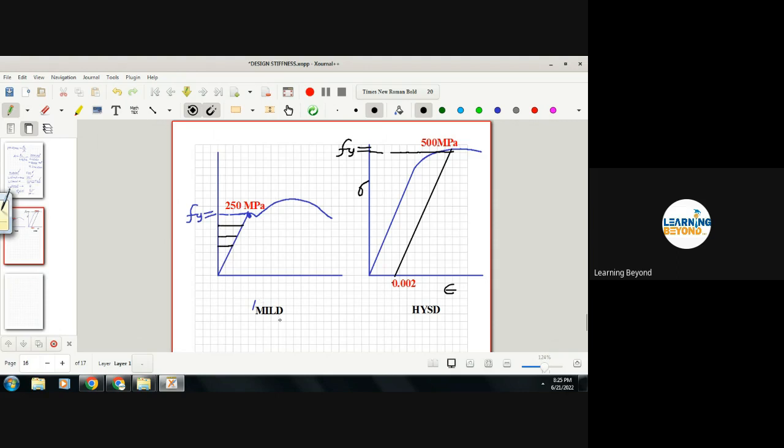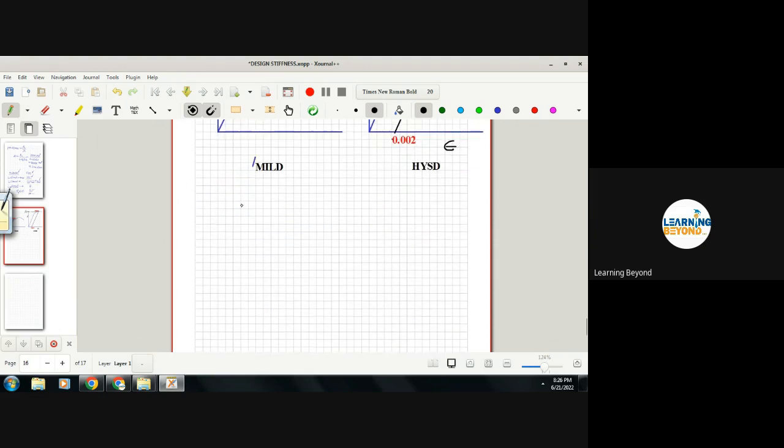If you are designing a steel structure in mild steel, our IS code is IS 800. Mild steel like ISMB, channels, beams, angles, all that kind of material we use in industries. We use ISMB 200, ISMC channels, angles, rectangular tubes, and so on. All that is mild steel having grade 250 MPa. And whenever we design any section, depending on the stresses or forces in the member, we have different permissible stresses.